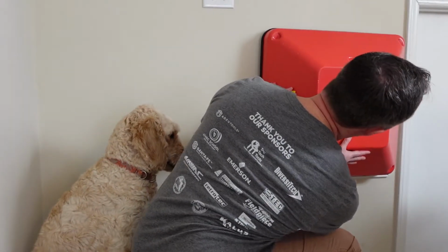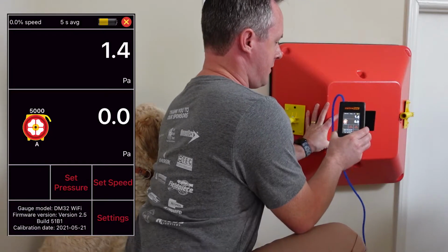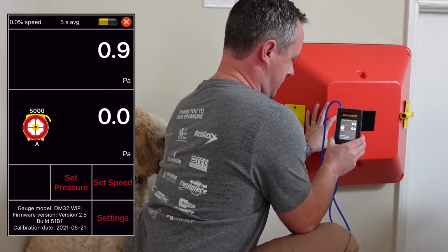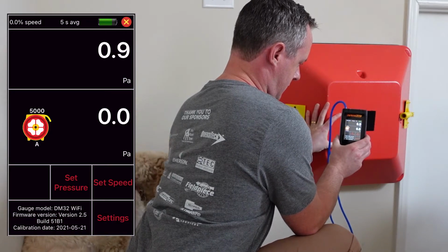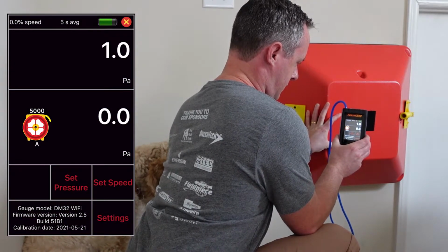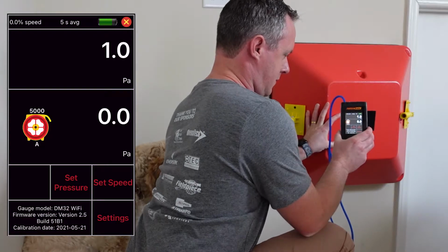And here we can use the larger one to put it over this return with the HVAC system off to maybe see if there's some leakage in this return somewhere, or maybe at the drywall rough opening, where we can see a pressure differential between this return area and the rest of the house.